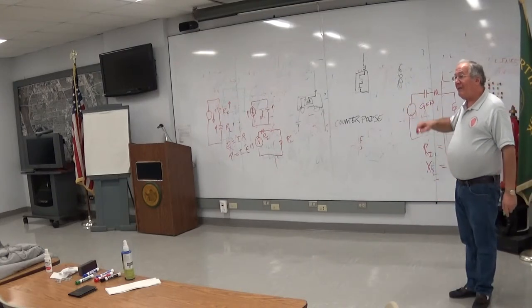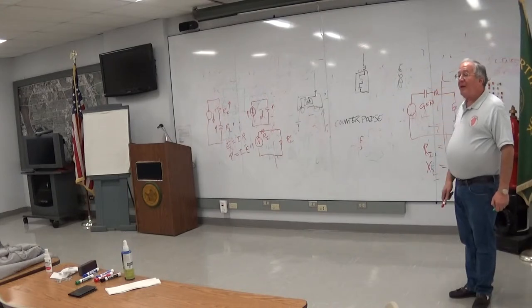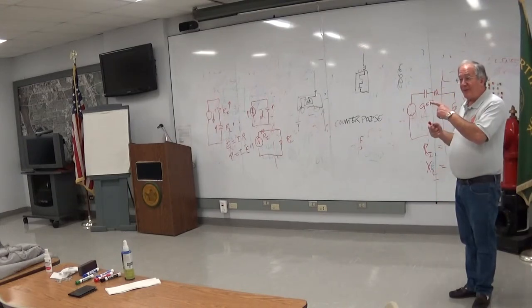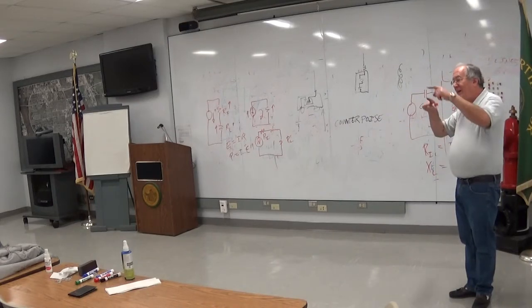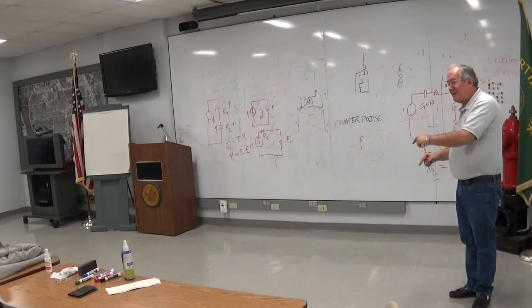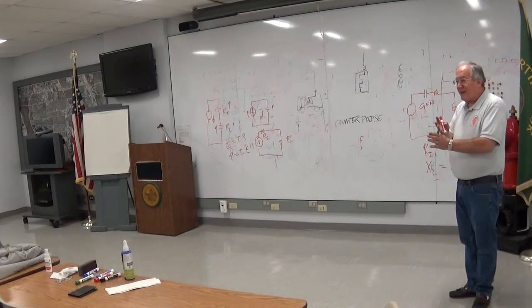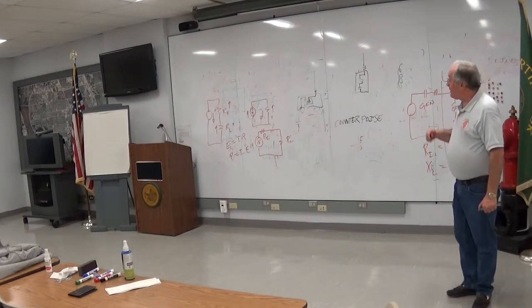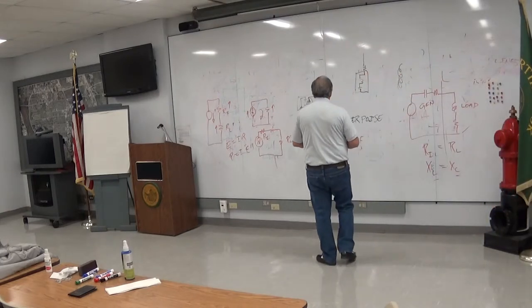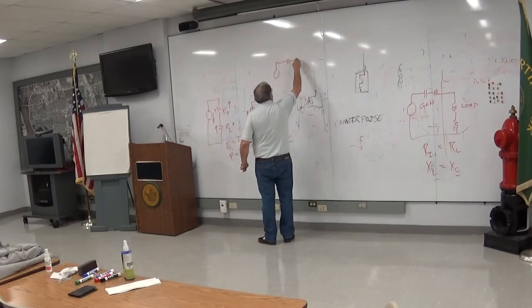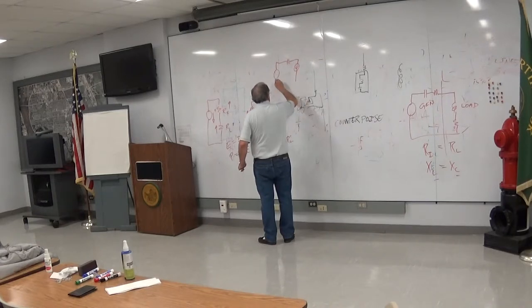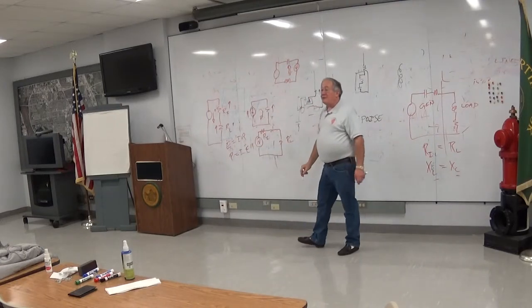If you happen to have your voltage leading, you're going to have less power because you have a power factor that we talked about, a shift in phase. You don't have the coincidence of the current and the voltage happening at the same point in the cycle. You want to pull those together. So what you want to do is do what this high school experiment did, where you have the capacitor, the resistance in the form of a light bulb, and the inductance. You want these guys to be equal to each other in impedance, so they cancel each other out.